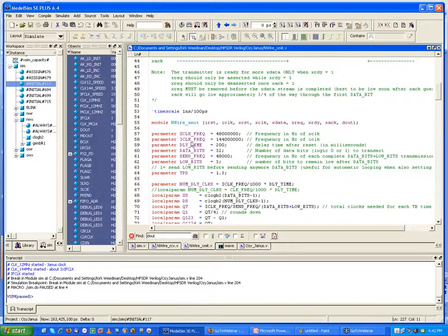But you can override them, because in other modules I use this, but I set these equal to the same frequency. I use the same clock. But in the Aussie FPGA, I actually use 2 different clocks. So I'm making this module, as you'll see, so that you could use the same clocks or different clocks. And I'll show you how I do that. Here I've said that all of these signals starting with the X are running at this X clock frequency, and the ones starting with I are running at the I clock frequency.